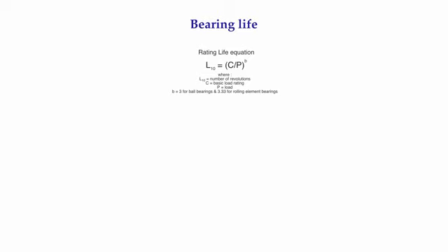Every bearing has a basic load rating shown in the rating life equation as the variable C. Some bearings are rated to carry 100 pounds of load, others 500 pounds of load, and others several thousands of pounds of load. A bearing might have a basic load rating of 100 pounds, but what is it actually seeing? 10 pounds, 100 pounds, or 200 pounds?